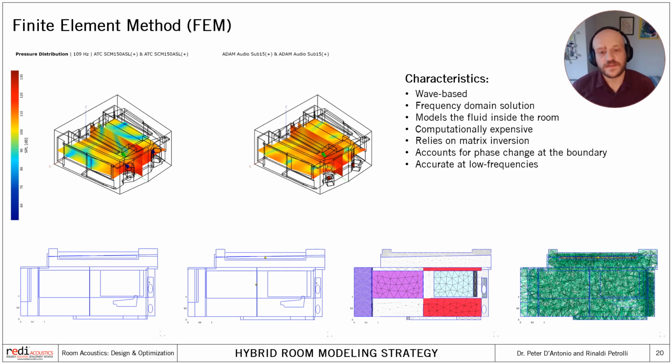This is a wave-based frequency domain solution, but we can also derive the time response by applying an inverse Fourier transform with the appropriate signal processing. While this method is computationally demanding due to the requirement for matrix inversion, especially at higher frequencies, the precision at low frequencies is really good. This is because we are using surface impedances to represent the room materials, meaning that we are accounting for the changes in phase occurring at the boundaries, which is a crucial factor for the proper representation of low frequency effects.